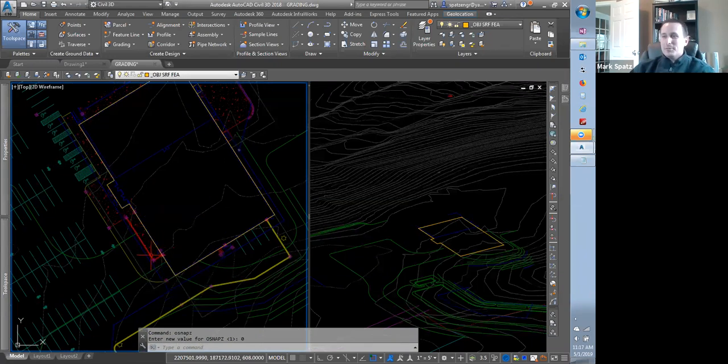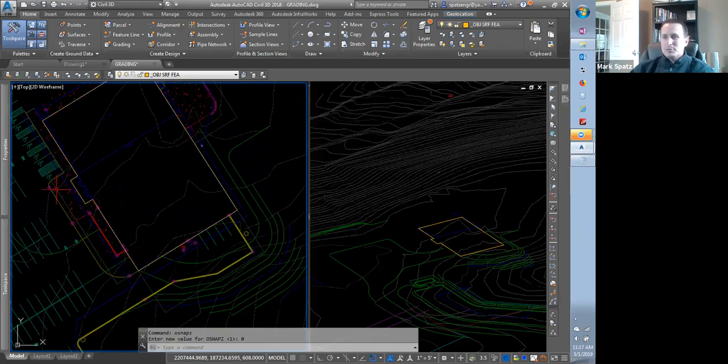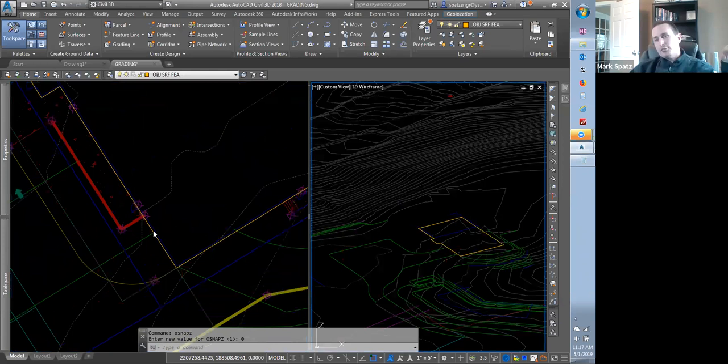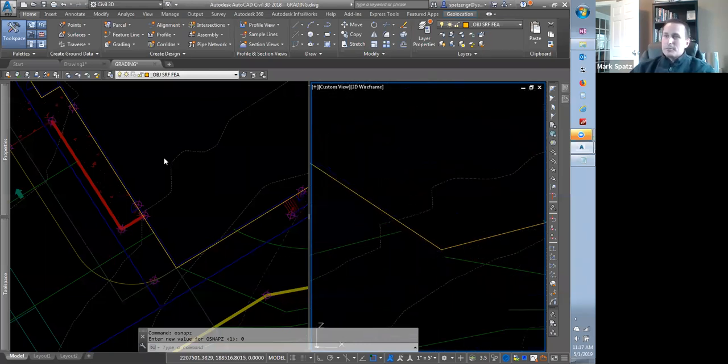So this is a curb. I'm going to assume, at least for our design, that there is going to be a 6-inch curb reveal here. I'm assuming the curb comes out to here, kind of juts back. Okay, that sounds good. So the first thing we need to do is get from this corner out. Usually curbs are 2%, like you have a 2% cross slope away from the building. You could do 1%, but I usually use 2. I think everybody uses 2.